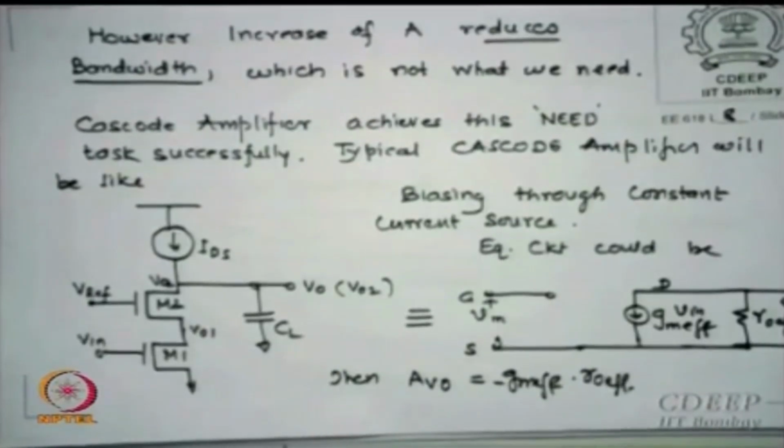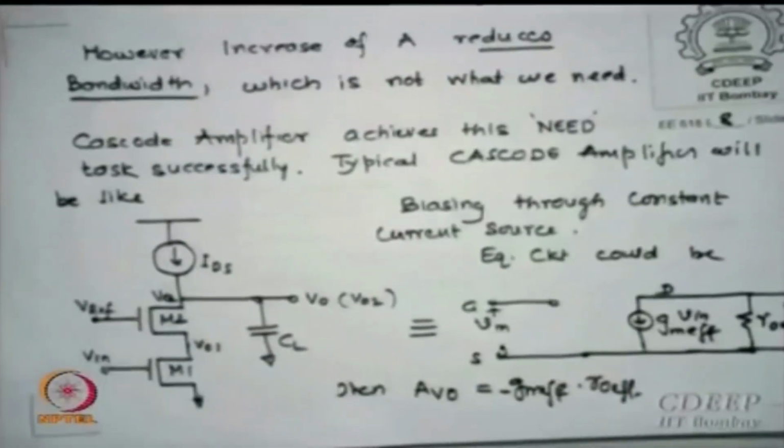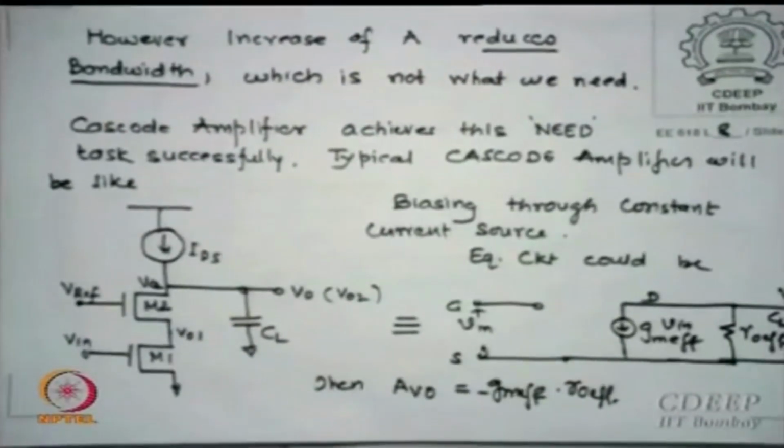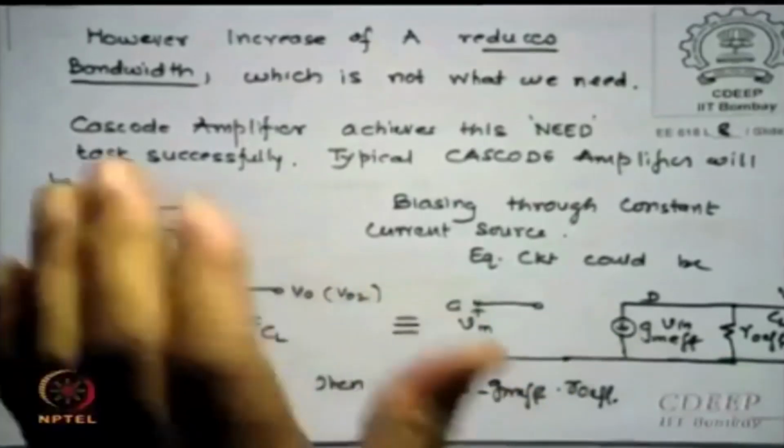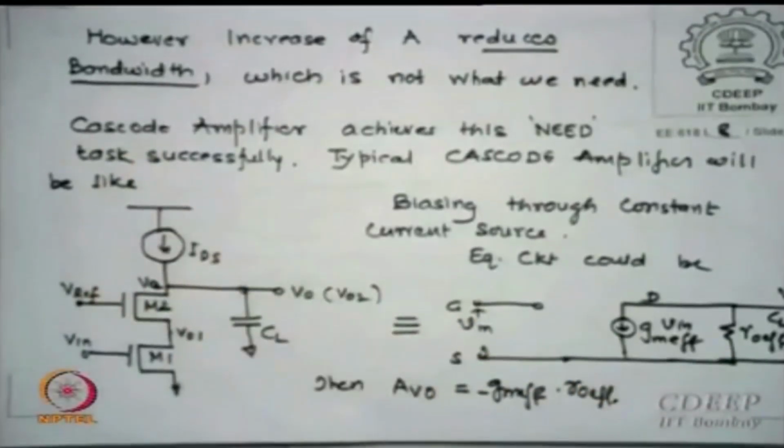It allows you to shift, let us say, what is the first stage doing? Raj, you look at it, M1 is a common source amplifier. So what is the common source amplifier's characteristic? Converts voltage into current. Common gate amplifier improves the output impedance, just now you have said, and still gives the same current. So what has improved? The current source equivalent, the voltage dependent current source, has become far superior compared to a single stage.